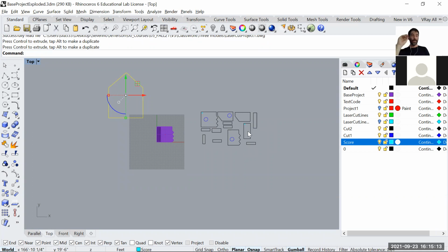Okay. AutoCAD 2D drawings, again, plans, sections, you can do the polylines, organize each of those polylines into the template, change the layers of that, send it to the laser cutting. You might want to take those polylines or those plans and sections, import them into Rhino, do the polylines in Rhino, organize them into the template in Rhino, send them to the laser cut.